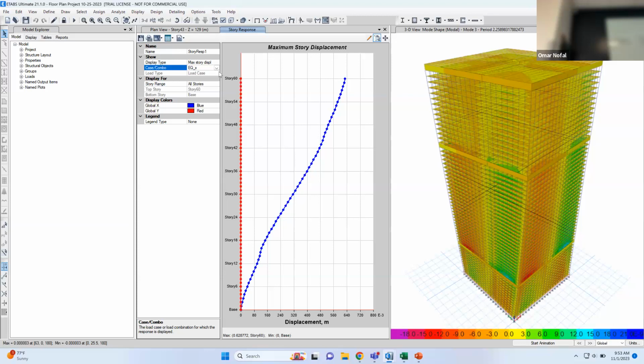If you want to go to the upper limit, you can put 600. So around 0.3 meters. So it's 30 centimeters. That's that level. So what I should do, I should add more shear walls, more things to make the system more stiff. But if you want to stick with the building that I give to you, that's fine.